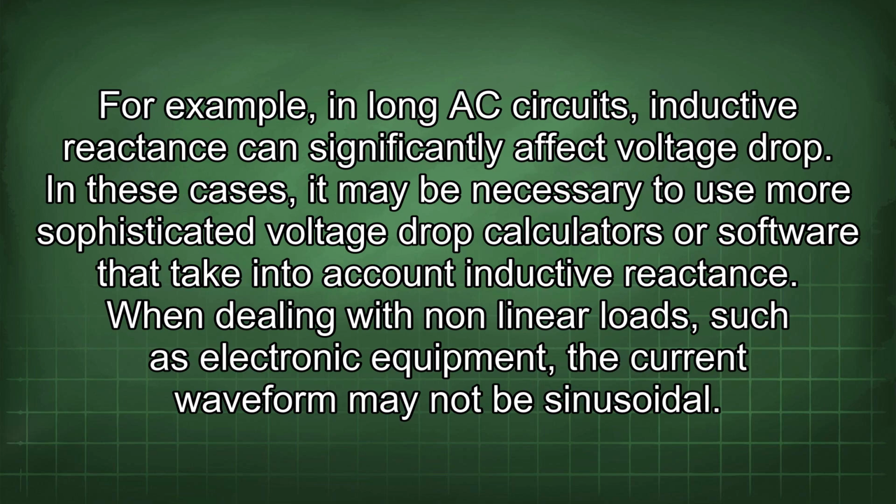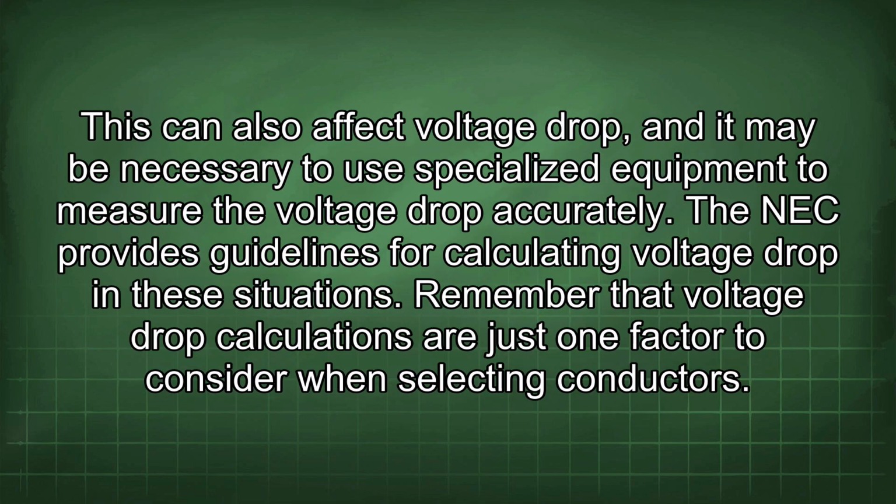inductive reactance. When dealing with nonlinear loads, such as electronic equipment, the current waveform may not be sinusoidal. This can also affect voltage drop, and it may be necessary to use specialized equipment to measure the voltage drop accurately. The NEC provides guidelines for calculating voltage drop in these situations.